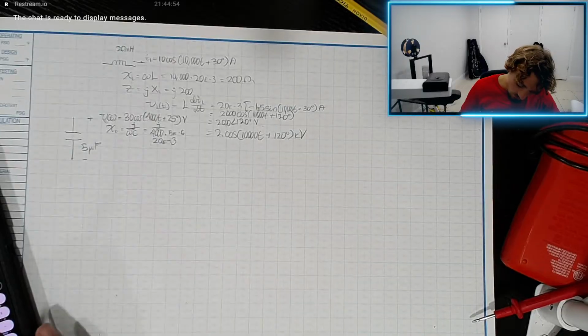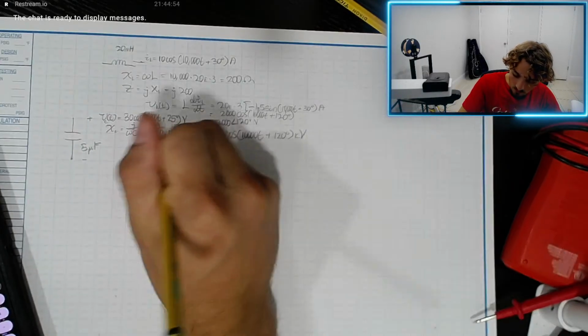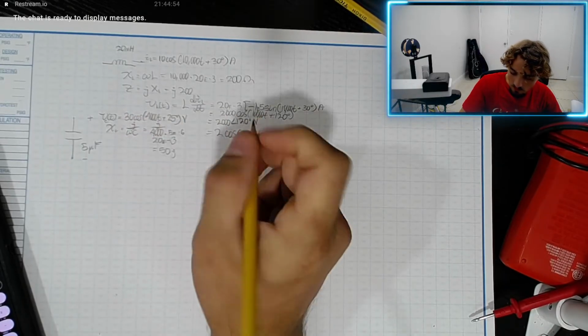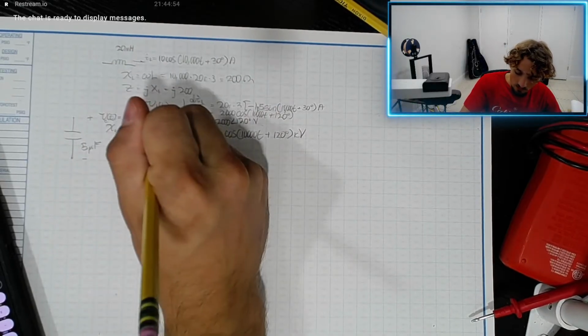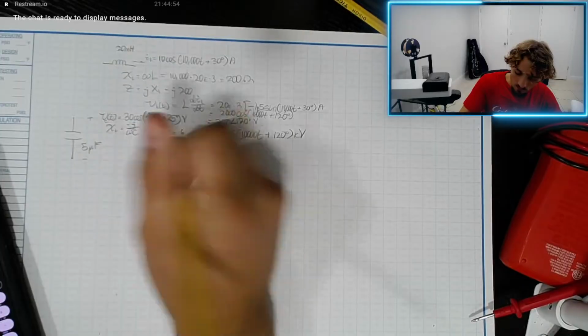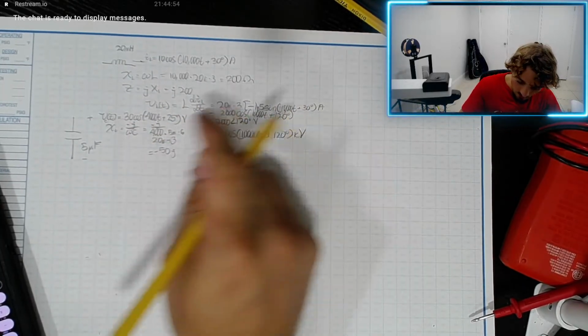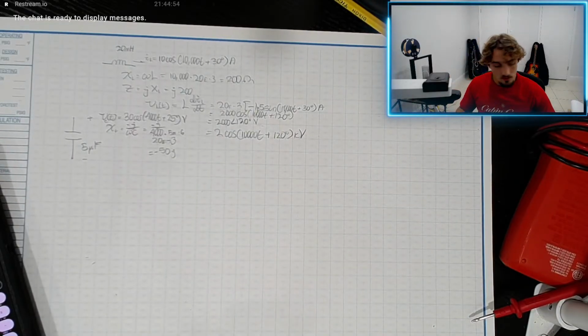Whatever, 1 divided by 20 e to the negative 3, 50. Okay, equals 50 j. Is this correct? Negative. Yep, for the capacitor, it's negative. Okay, negative 50 j, an imaginary number. All right, cool. So that's just simply the reactance.